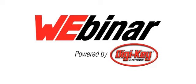Yes, it looks like we do have one here. In an application using a surface mount fuse holder where the current is very close to the fuse holding current, what are the best practices for layout and enclosure to minimize the temperature rise and life derating? Yes, in this case, you also have to take care of the cable. Please use the biggest square section of the cable which is possible, and then you can use your fuse regarding the hottest temperature which is suitable for the fuse holder and the fuse, and the cable will dissipate the heat out of your system. So here it is important to use a big square size of the cable and to put the cable a little bit away from the connector itself or from the fuse holder in this case.